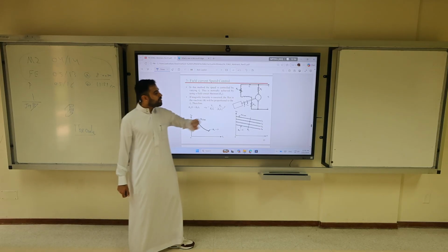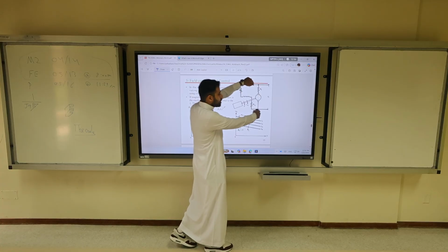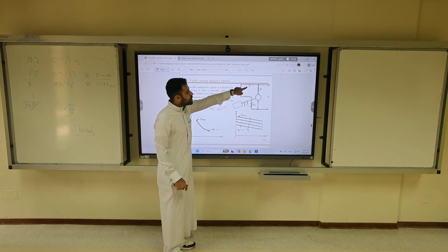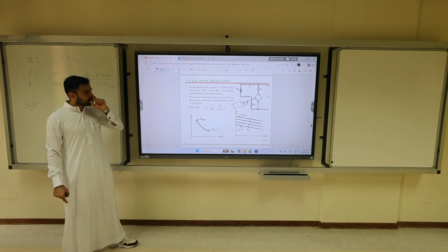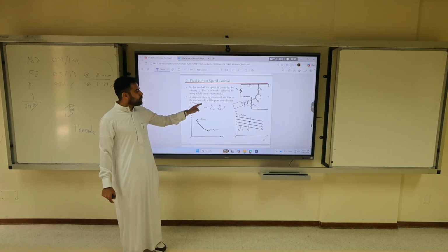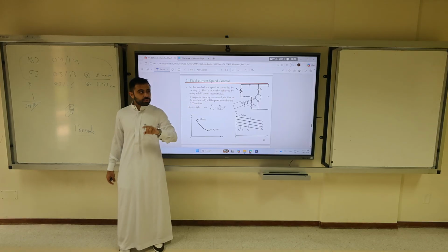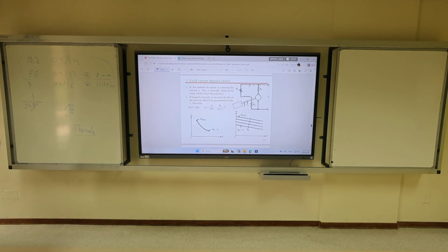So they have another resistance, they change it because here you apply terminal voltage, the same voltage. The only way to change IF is to change the RF. If magnetic linearity is assumed, the flux will be proportional. So we assume, do you remember the flux IF curve?